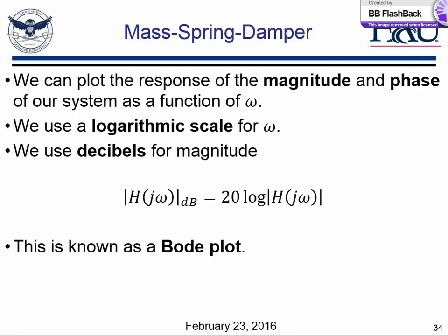So when we plot the response of the magnitude and phase versus a driving frequency or input frequency to the system, we use something called the Bode plot. So how many of you guys are familiar with logarithmic scales? Right? We're all familiar with logarithmic scales. We use a logarithmic scale to denote our frequency, so we have a broad range of frequencies that we're able to look at. We also use a decibel scale for our magnitude.